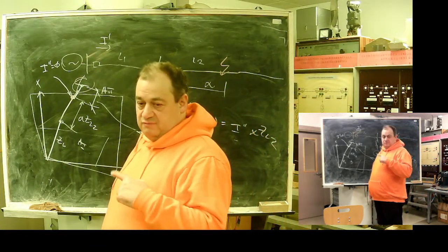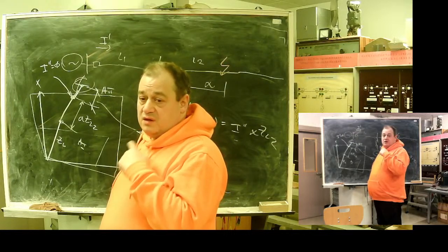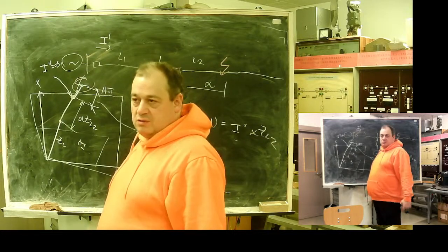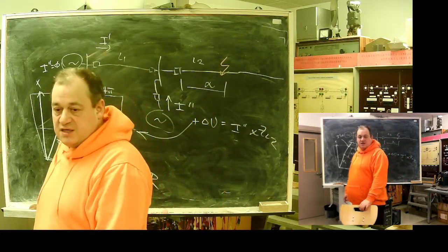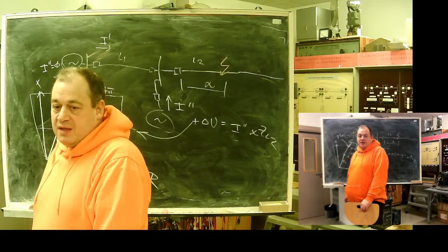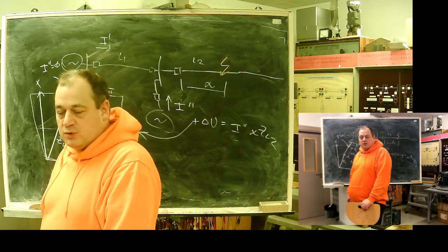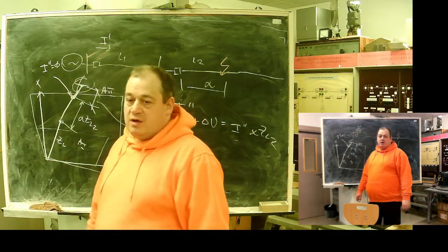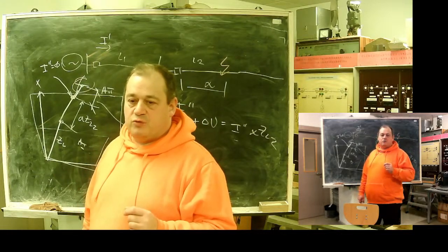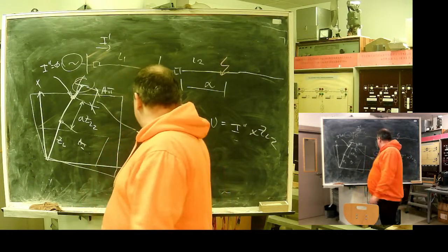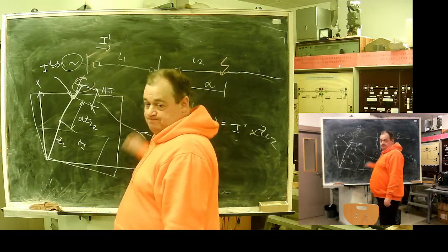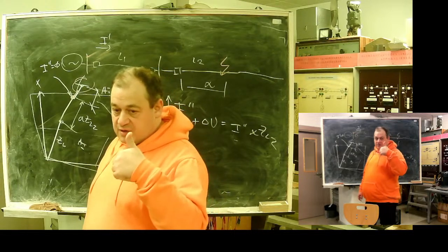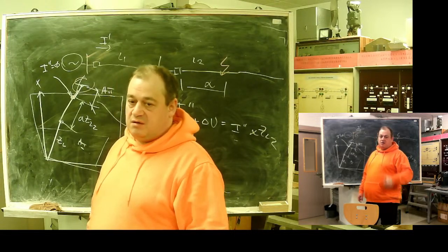If you are pushed by something to take a lower value, closer to the network's normal regime, when this source is operational, you should very carefully check what happens if this protection trips first. The current distribution factor will instantly rise to 1.